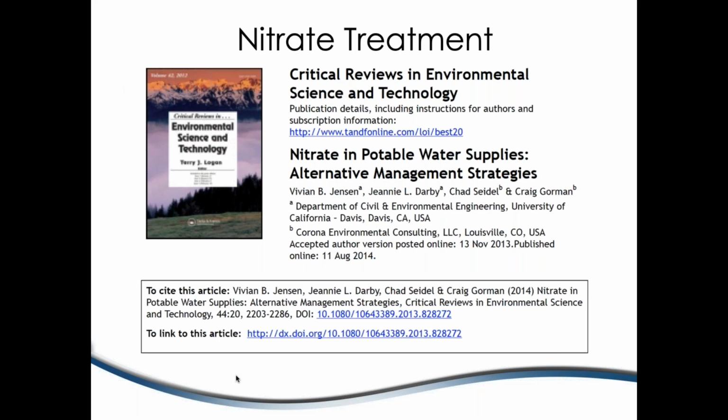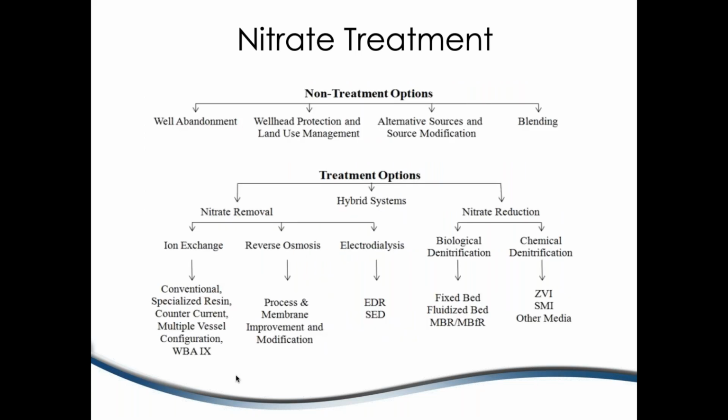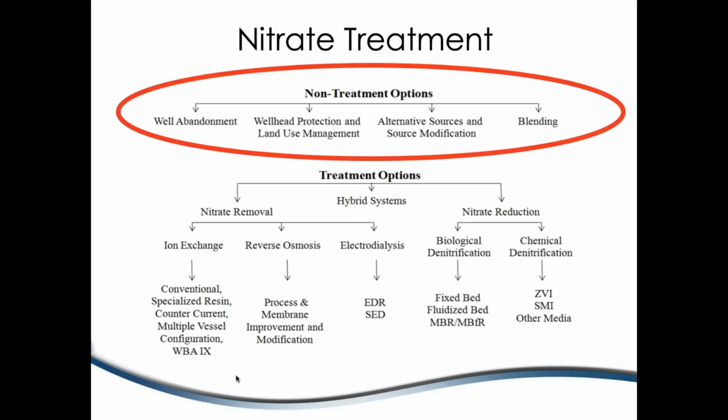Frankly, this project is an outcome of those realities, because if we think about nitrate treatment in a big sense, the first thing you want to do if you've got a nitrate problem is avoid nitrate treatment. Figure out how not to have to implement nitrate treatment, because it's a challenge, even more so for smaller systems. So consider other supplies, consider blending, consider ways you might just avoid the nitrate treatment in the first place.